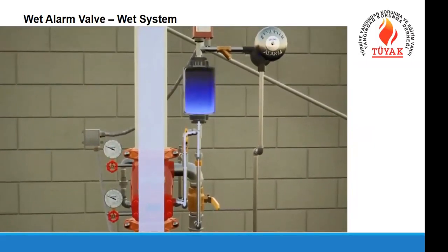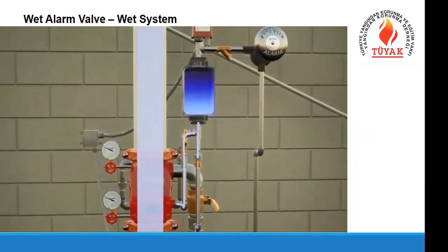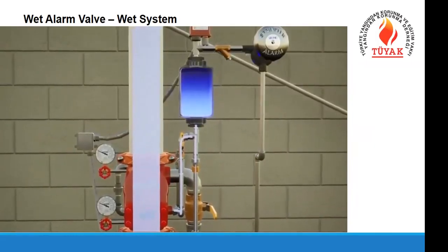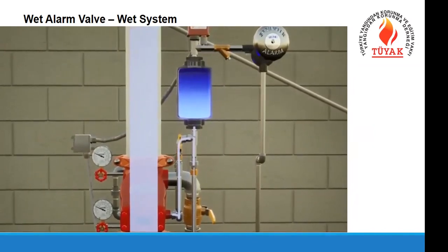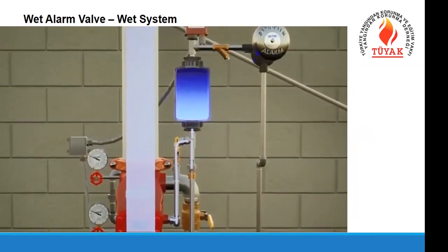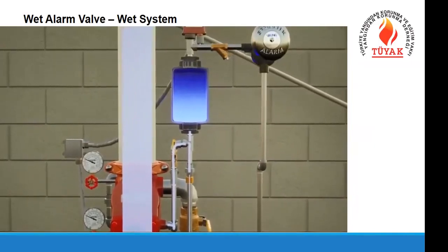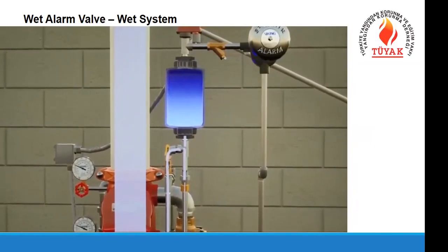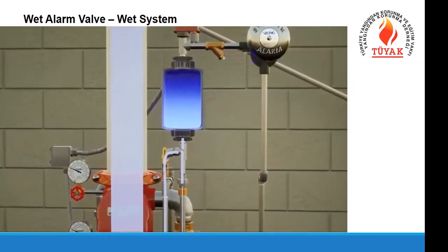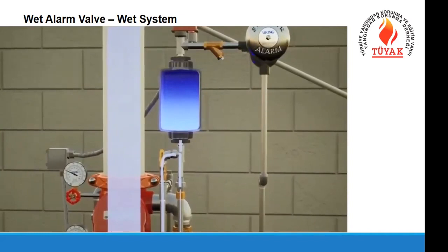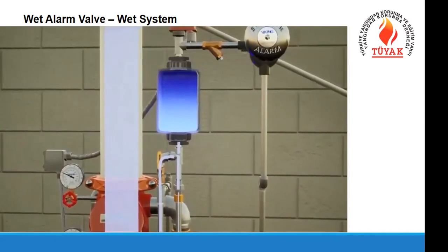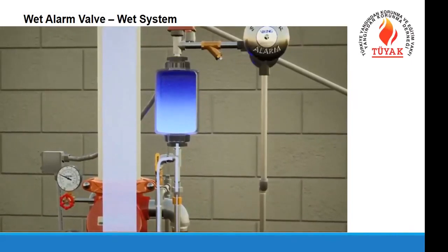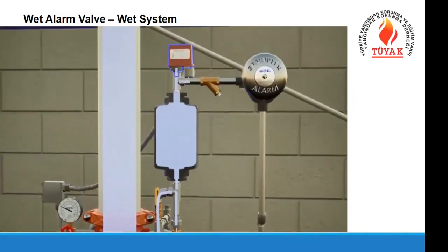The retard chamber is a device that prevents false trips by containing up to a gallon of water flow prior to creating an alarm. Inadvertent water flow will only be able to fill a portion of the retard chamber's capacity. The alarm line is equipped with a 1/8 restricted orifice that allows the retard chamber to externally drain and reduces false alarms. During a fire, a consistent flow of water enters the alarm trim and fills the retard chamber faster than the restriction can drain, and the water flow continues through to the alarm devices.